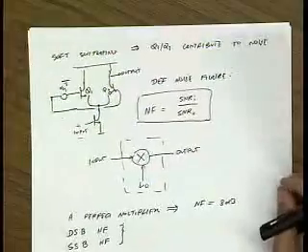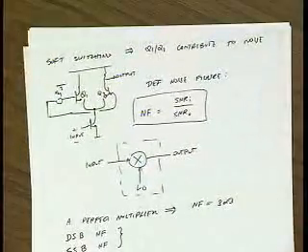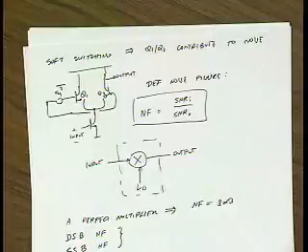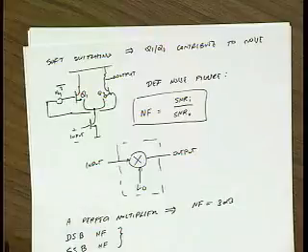Question. So basically, you said that the thermal noise is constant all the way up to 1 terahertz or whatever. So basically, all the harmonics that you have there up to that point would contribute. That's true. So basically, depending on the number of harmonics you have up to that number. But a perfect multiplier, right? That wouldn't apply for a perfect multiplier. But for any real mixer that's a time-varying circuit, you have to take that into account. Yeah. So in this case, it's going to be humongous. No, it'll probably be about 8 dB, 9 dB, depends.